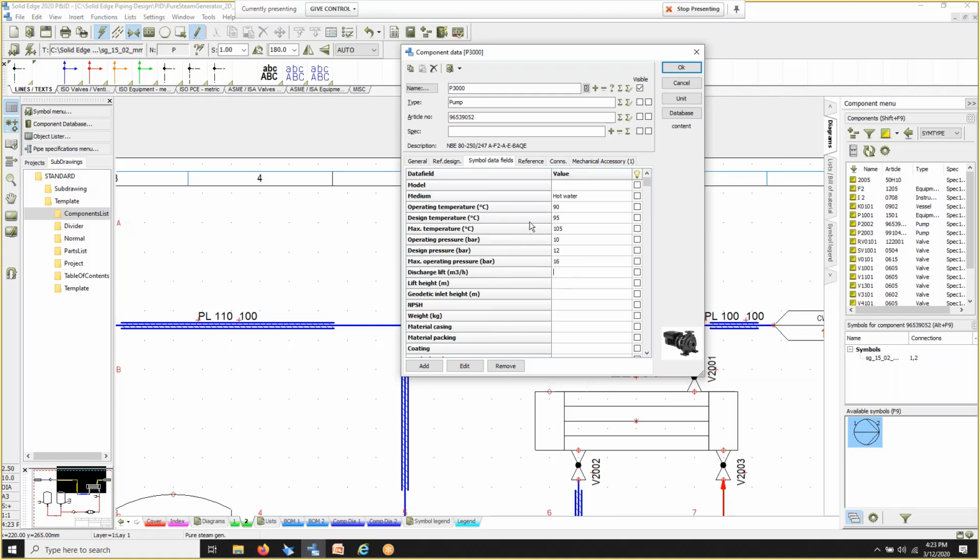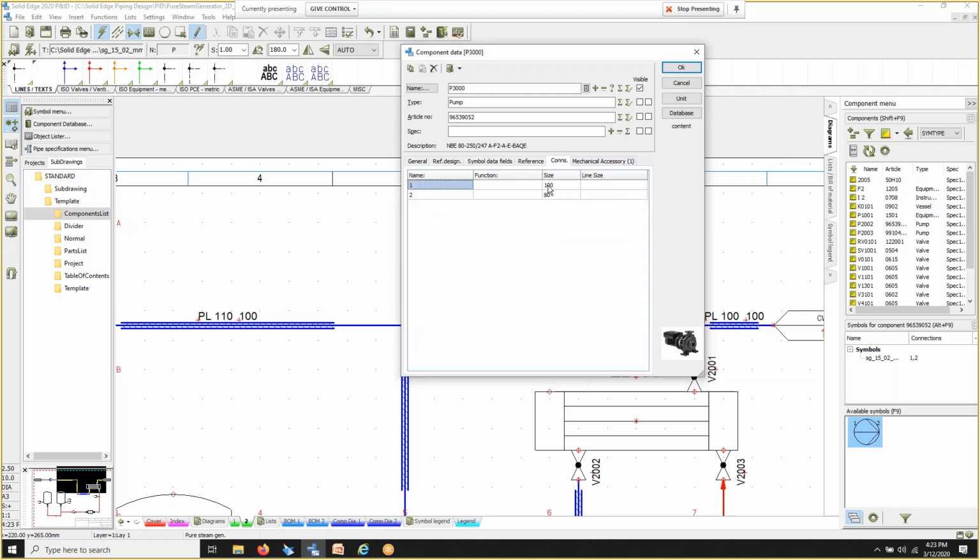And so all of these pieces of process-specific information are tailored in here to remember what type of component you're using, so it's going to have these saved in there, but you can add your own or remove them, change names on the fly as you wish. All right. Also, what connections, so it knows what size the inlet and outlet is of this pump, as well as we need more than just a pump whenever we go to order this. We also need the motor that goes with it.